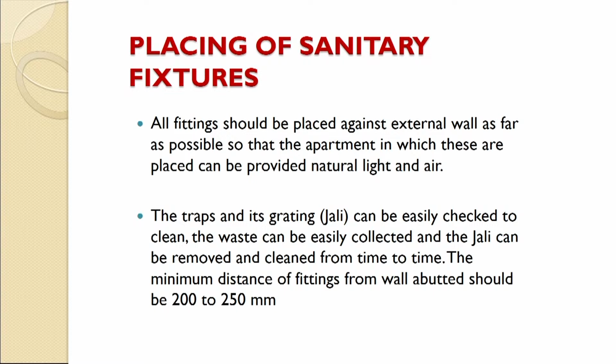You can do it yourself as a family member, but the space is not available. You can't remove the jali or the grating easily. So, as a plumber, you should try to put the grating or the trap so that it can be cleaned easily.